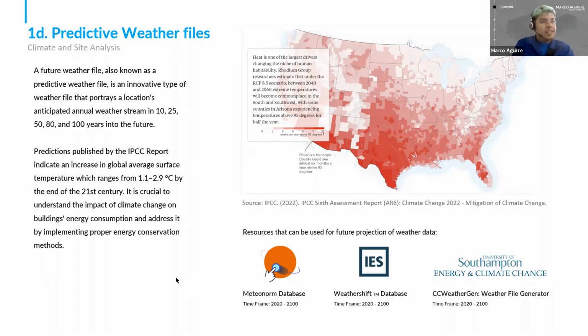All great sources. And if you have access to the load modeling tool, or if you have a trial with load modeling, you do have the ability to upload your own weather file, including a future weather file, to run analysis on your project. But it's going to be really important, as we see shifts in the climate, to understand what the anticipated weather conditions will be so we can better design towards them.